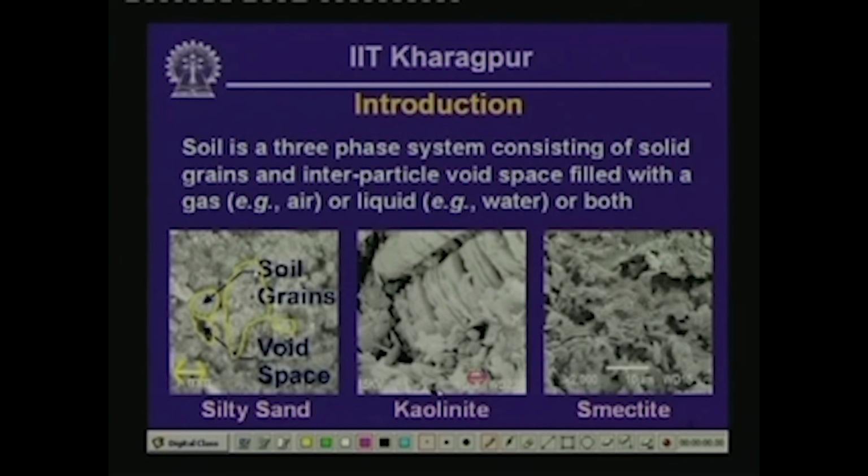So you can see that this is a much enlarged view of the soil structure. Now this one here is a photograph of kaolinite clay. We talked about the chemical nature of kaolinite clay. What I want to draw your attention to is that what you see here is essentially a stack of plate-like particles, and again, as earlier,